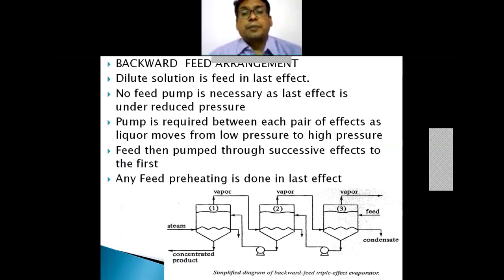Now, in this multiple effect evaporator system, the backward feed arrangement, forward feed arrangement, mixed feed arrangement, and parallel feed arrangement are the different arrangements provided. In the backward feed arrangement, the feed, that is the dilute solution, enters the last effect.